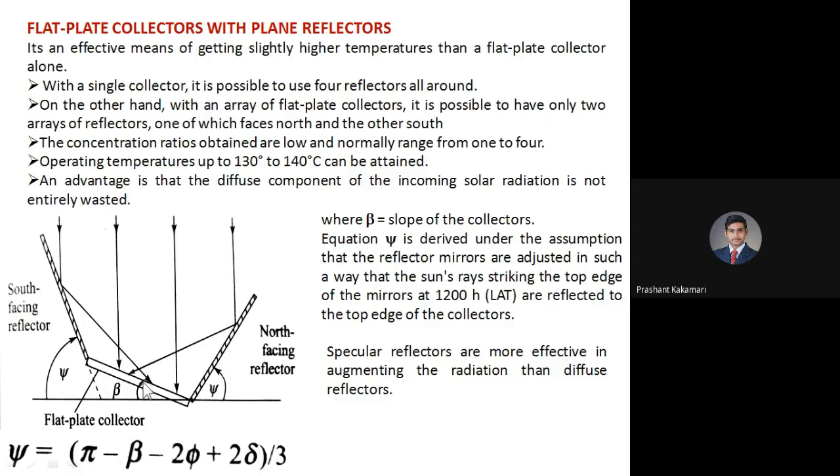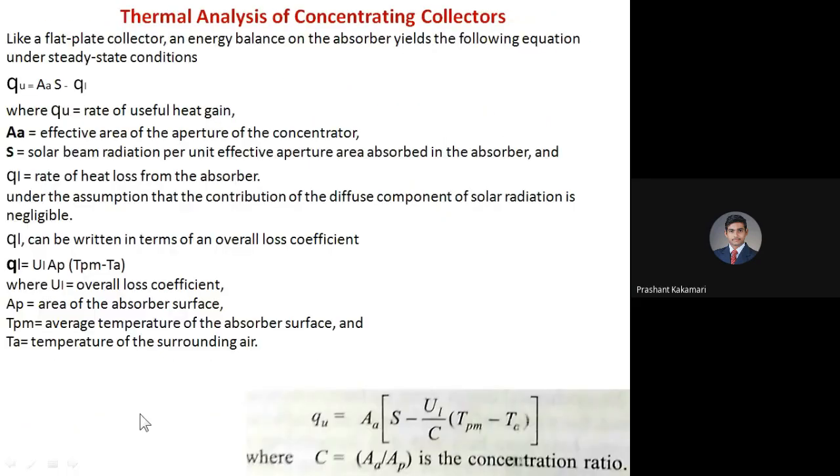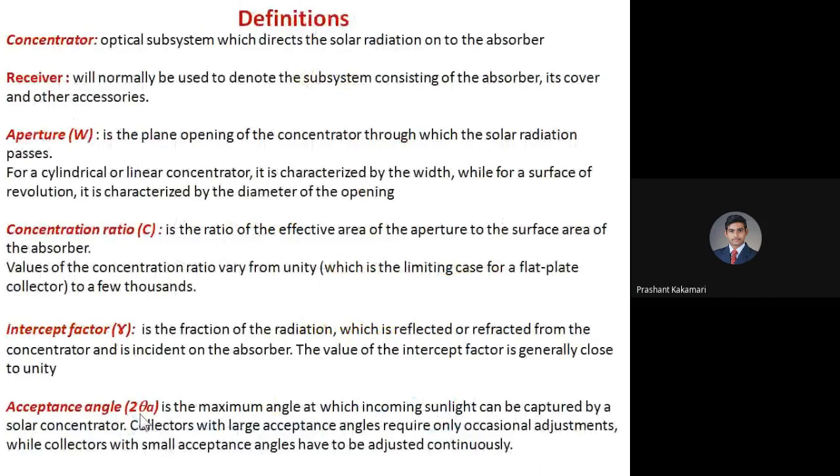Then what about the absorber area? Absorber area is the flat collecting area, which is almost considered equal to the cover area. So here in the flat plate collector, cover area is also equal to absorber plate area. So that only I can consider as receiver area. So to take this ratio, that I can define as concentration ratio.